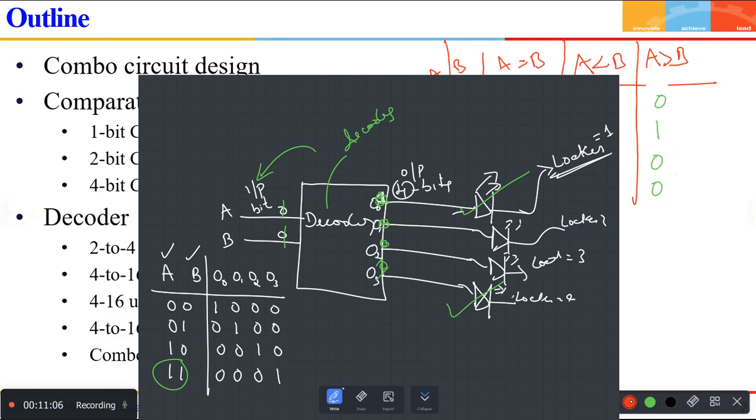Sorry, 16 outputs can be taken from a 4-bit input combination. So have you understood this decoder action? It decodes. Suppose your code is 0, 0, give that input, it decodes in such a way that O0 will open. With 0, 1, O1 will be 1.